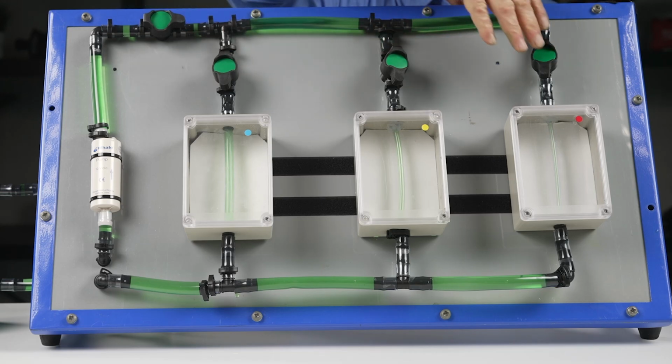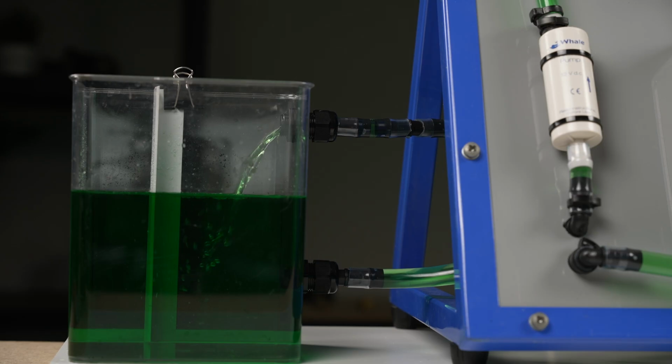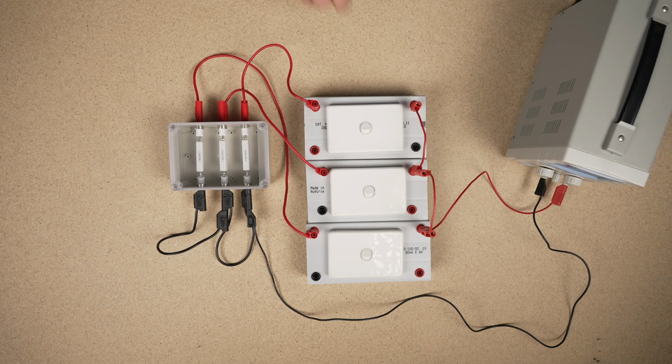In this configuration, the same pressure is applied to each resistive element in the circuit, and the flow in each resistive component is now determined by its resistive value. Now, let's look at our water circuit. With one element in the circuit, the flow rate is determined by that one component. The lower the restriction, the greater the flow. We see the same response in the equivalent electric circuit.